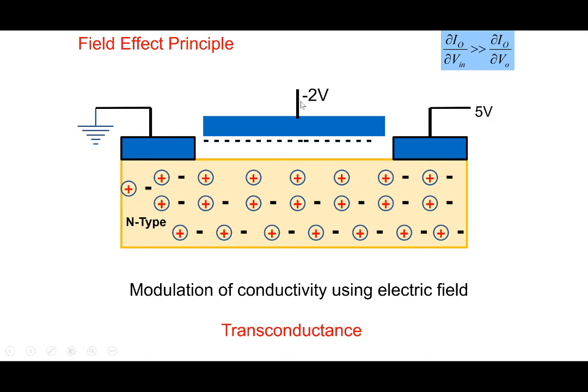And we can also see transconductance being there. The voltage is being applied between this pair of terminals. If we take this as a reference, the voltage is being applied between these two and is altering the current flowing between these two pairs of terminals here, right? So the current flowing in this particular terminal is being controlled by the voltage being applied here. That's the transconductance feature. And of course, we need to show that for this to act as a transistor, the current flowing here should be very sensitive to this voltage and not very sensitive to voltage over here. Then it would act like a transistor.